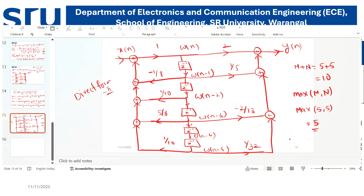Therefore, the number of memory locations required in direct form 2 has decreased from 10 to 5. That is the advantage of this direct form 2 structure. The number of memory locations required is less. If memory requirement is less, it is less in construction. If delay elements are less, then complexity will be reduced. The circuit will give fast output. These are the advantages of the direct form 2 structure.